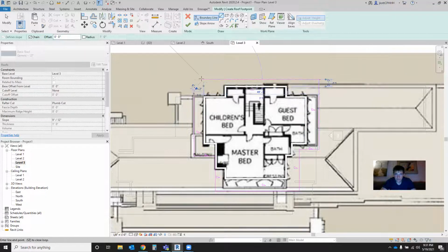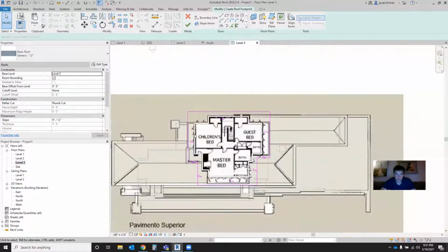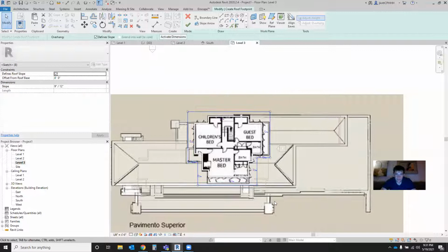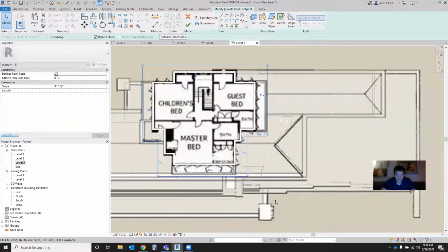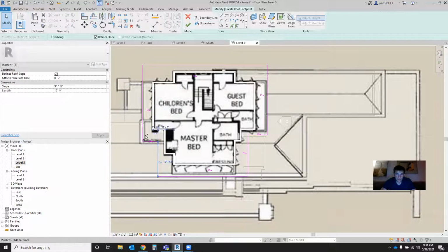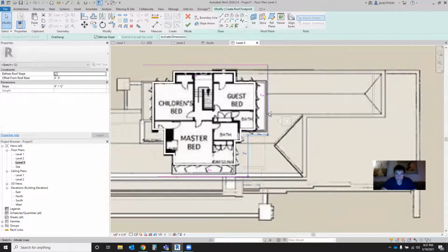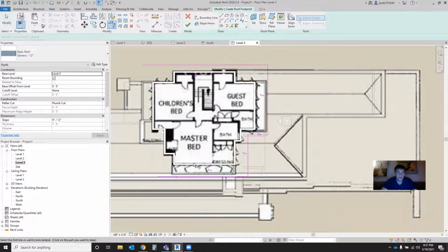I think it's something like this, and we can adjust this as we develop from elevations. All right, I think we might run into a problem if we don't actually mirror one side of the roof. What ends up happening is you don't have the right angles to have a smooth slope. So we just mirror the one side.